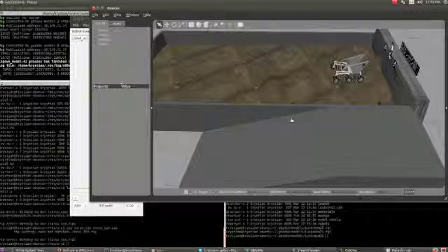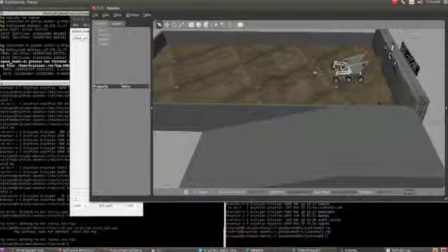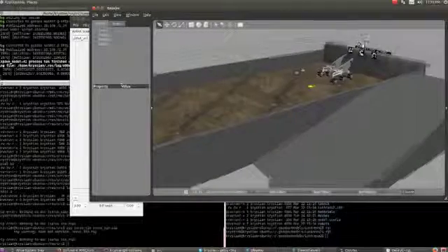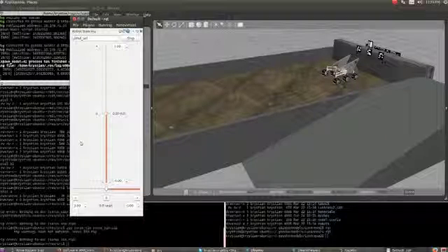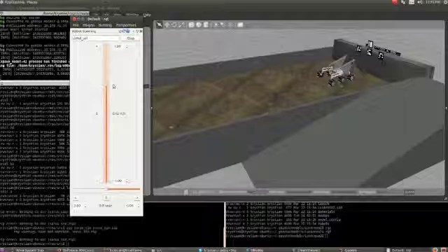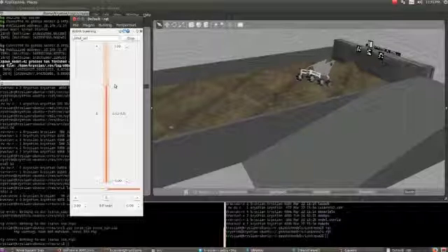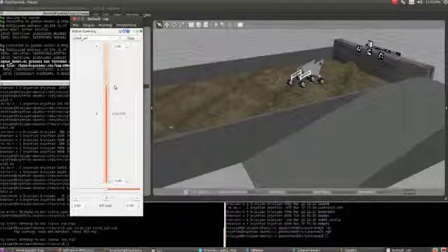Hello, in this video we're going to look at the process for creating a simulation using ROS and Gazebo to simulate a robot featuring closed kinematic chains. Because of the ease of use, we will use the SOLIDWORKS URDF plugin to export the open kinematic chain structure of the robot, then take this information from the CAD to create an SDF, which will be capable of simulating these closed kinematic chains. Although if you understand the concepts presented, it is possible to create an SDF directly without using this plugin.